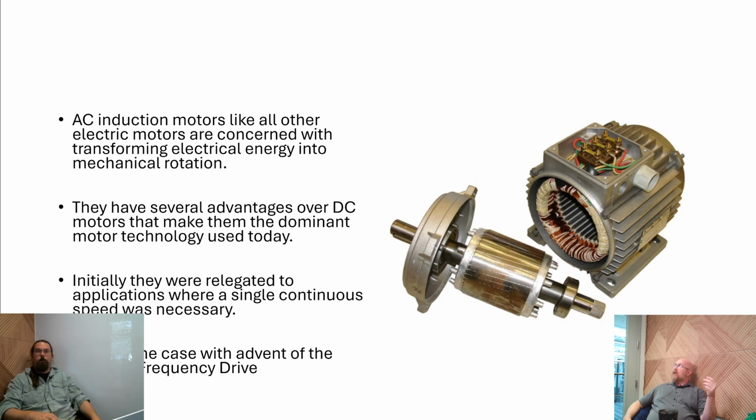What you see there are those bars that are going across. That's the squirrel cage that they're talking about. It's just a descriptor for what that is, and it's aluminum bars that create eddy currents when induced, and then surrounded by steel or iron, which allows magnetic fields to conduct through them.